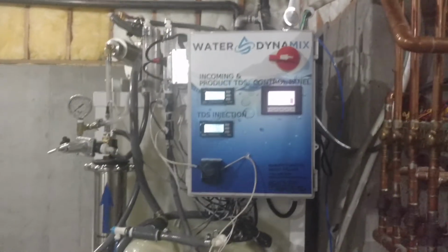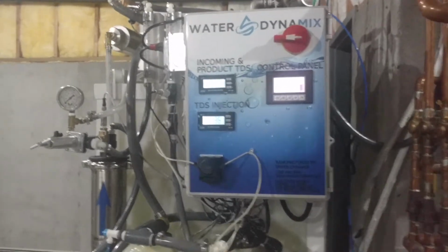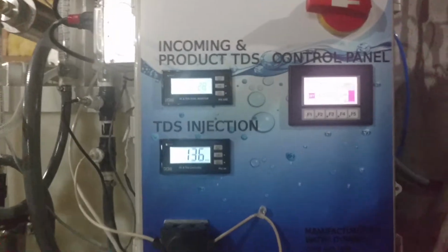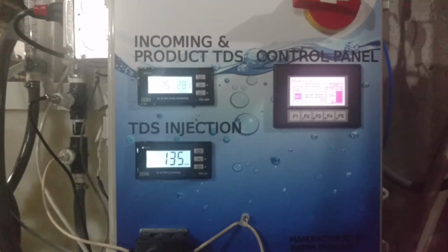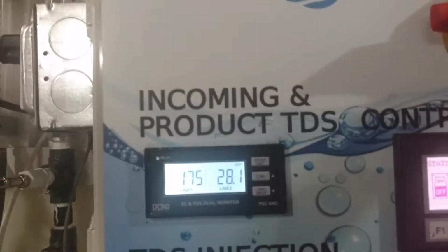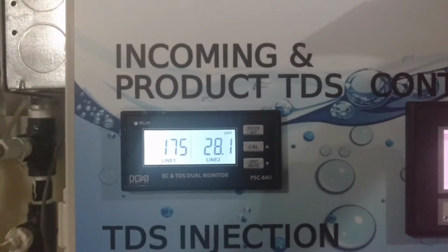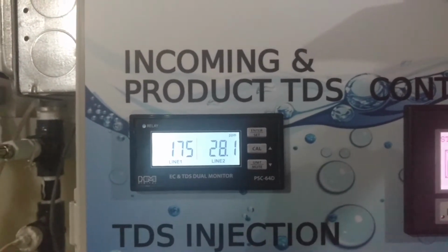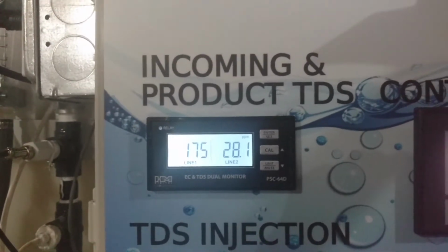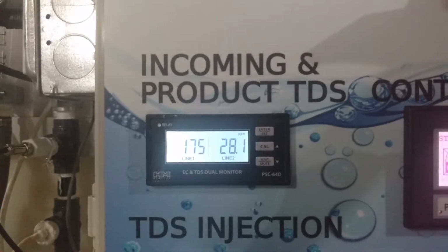Okay, so today I'm going to show you a quick overview of the Water Dynamics control panel. Before we start, I wanted to let everyone know that all these controls show their data in real time. To get started, we will start off with the incoming TDS and product TDS. Line 1 represents your incoming TDS, that is the incoming water supply. Line 2 represents the product TDS, that is the TDS in your holding tank.